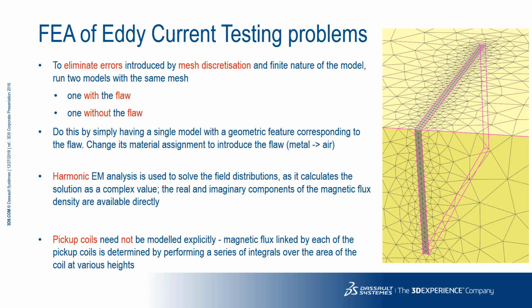Finite element analysis, or FEA, is a numerical analysis technique. The domain is meshed using the finite elements of the process's name. The mesh will give discretization errors due to the approximations involved in the numerical solution process. These can be reduced by using more elements, mesh refinement as it's called, but they can never be completely eliminated.